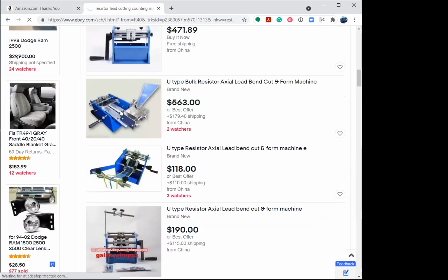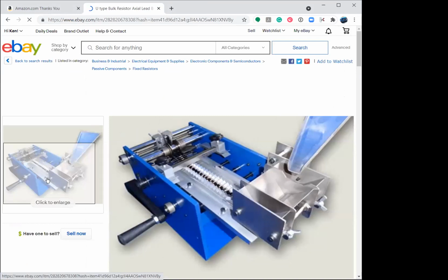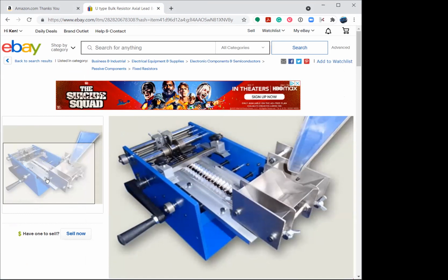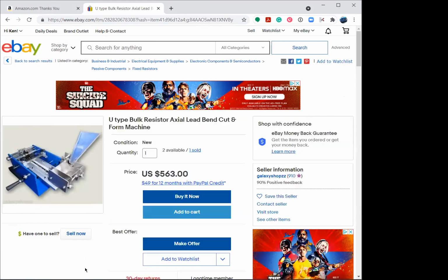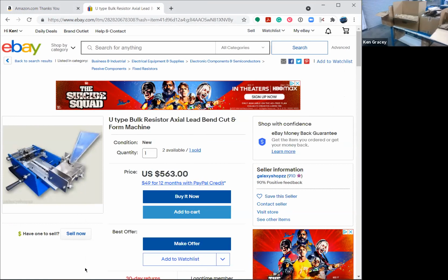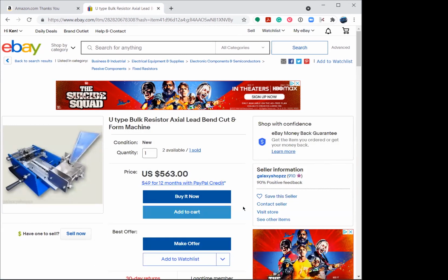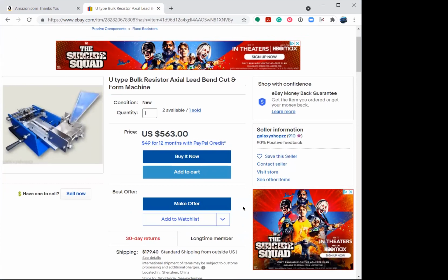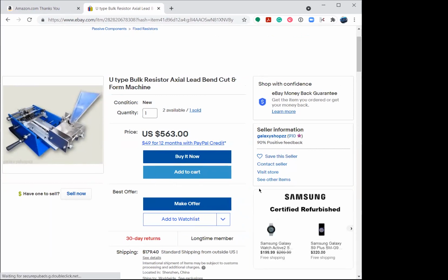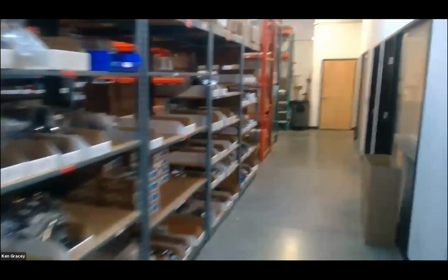And watch out for the glue, because that glue spreads like honey, and will upset your solder machine very, very easily. Okay, these are going in breadboards. Yeah, we want to get rid of the glue that's on the tape side of things. Please be careful when you handle, because the moisture in the hands or in the fingers will soften the glue, and the glue starts to spread. I see. And then it's honey.